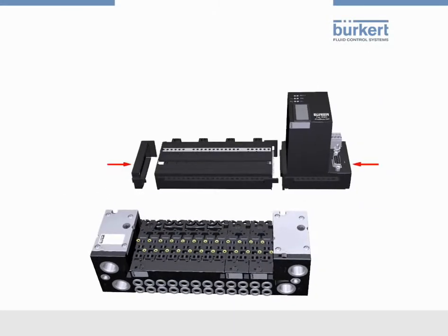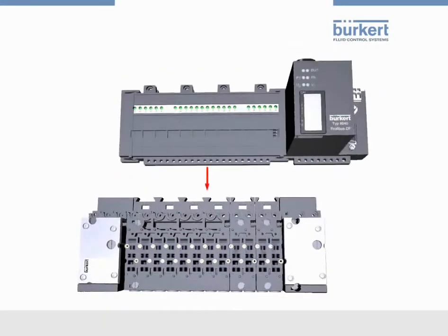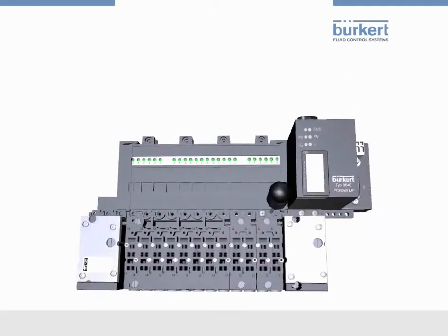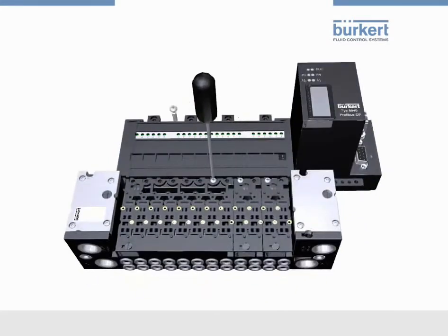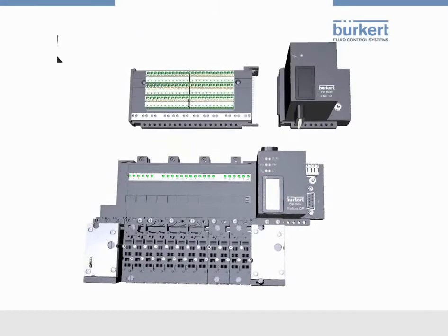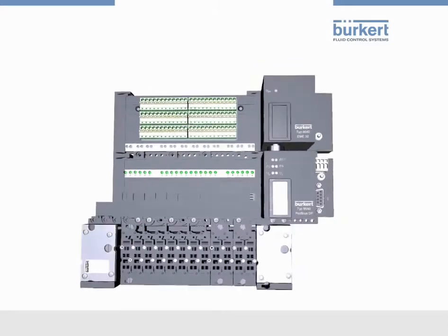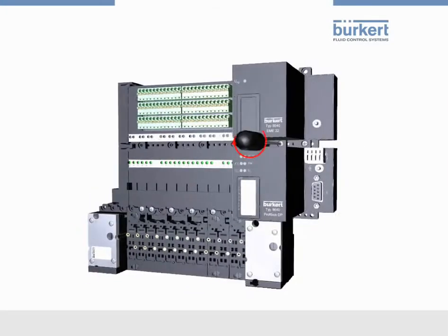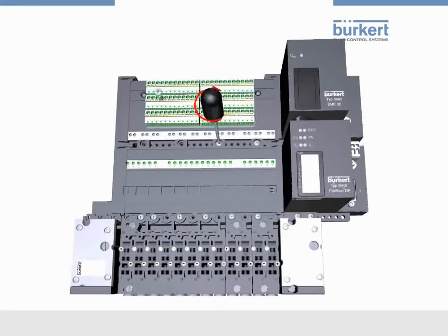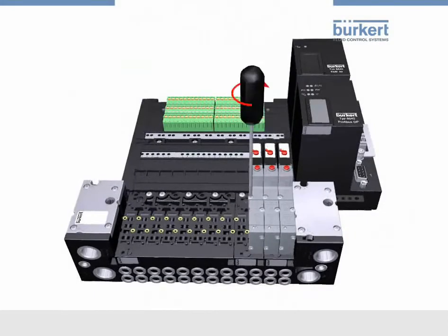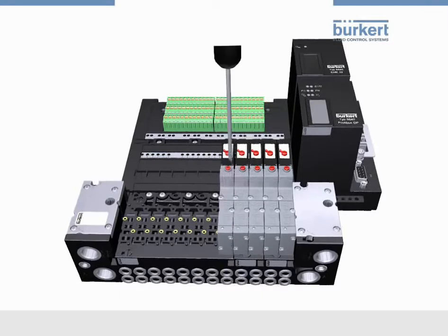In the next step, the communication module, as well as the electrical basic module for the electrical power supply, are mounted. The electrical connection technology allows a field bus interface, common connection, or multi-pin interface. In the new layer, you can add digital feedback inputs. A valve island uses these digital feedback inputs, for example for the processing of sensor signals, and uses the pneumatic outputs for the control of single and double-acting actuators. During the last step, the valves are mounted on the pneumatic basic modules.